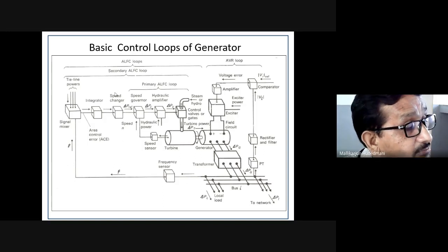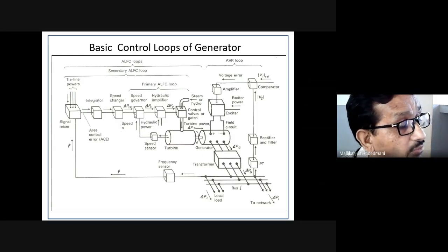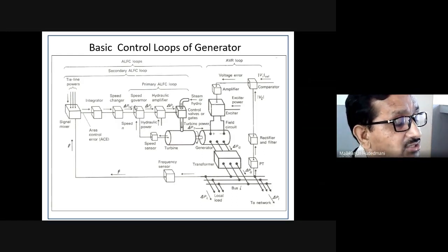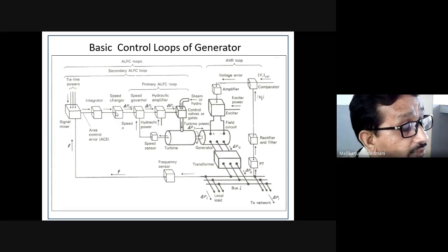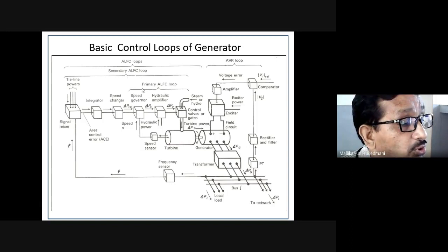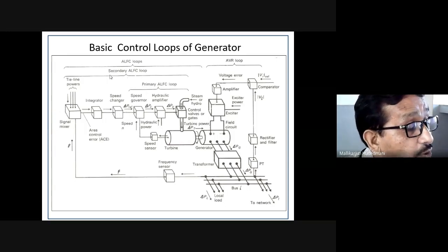Stimulus is speed. This is a request. This request makes a change on the governor. Governor needs to now act on shifting changes. So therefore, the integral controller on the power signal mixer works to request a change in speed by the speed changer. Speed changer accordingly makes the correction to the governor. So input to the primary loop is a control output from the secondary loop.